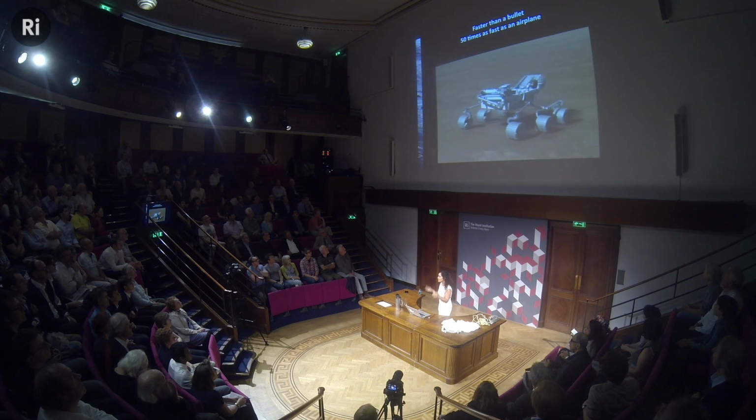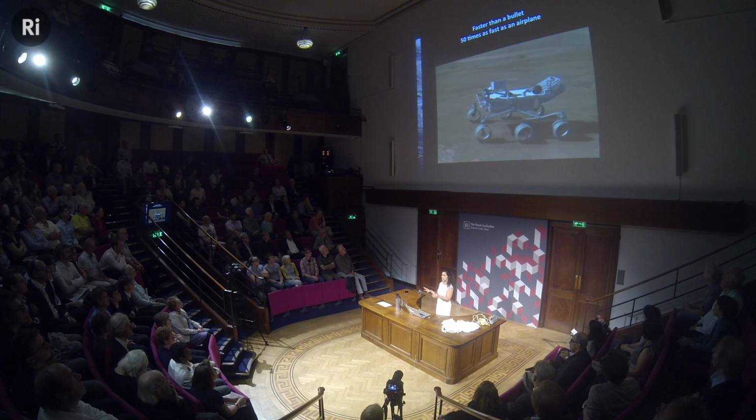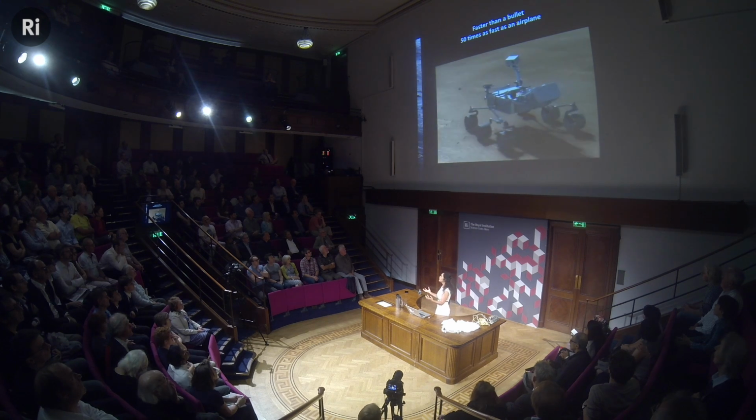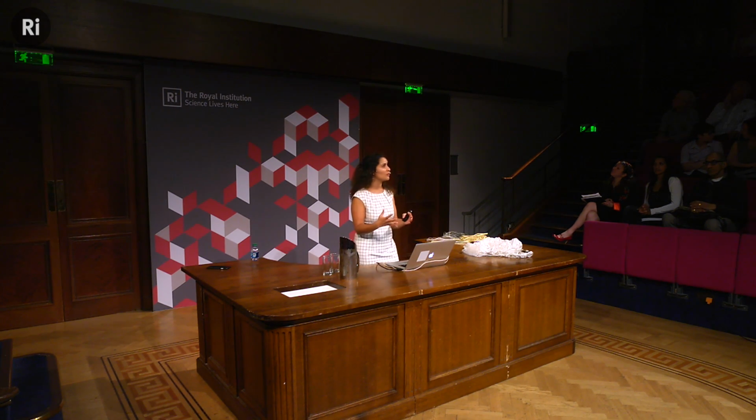So what makes Mars actually nice from a landing perspective is that you don't have to carry as much propellant with you because you can actually use the atmosphere to slow you down. If anyone has put their arm out the side of their car when you're going down a motorway and you feel the force on your arm, that's aerodynamic drag. So we use that principle to slow ourselves down to take out roughly 99% of the energy coming in. The rest does have to be taken out using retro rockets, but the atmosphere does help you in that sense.